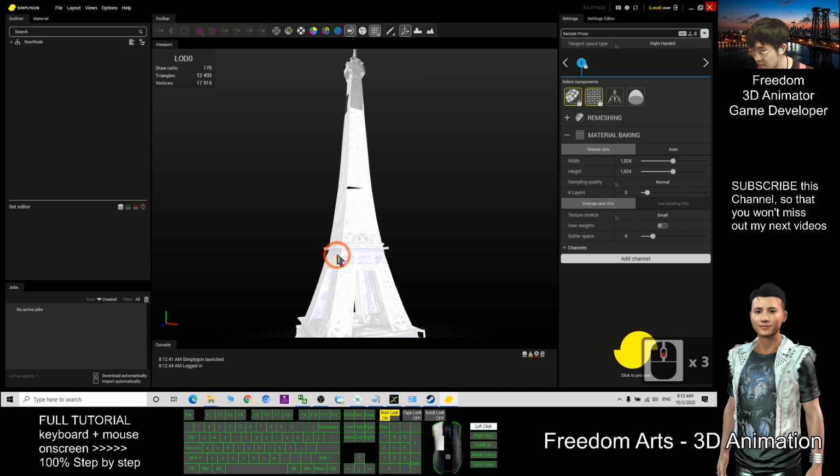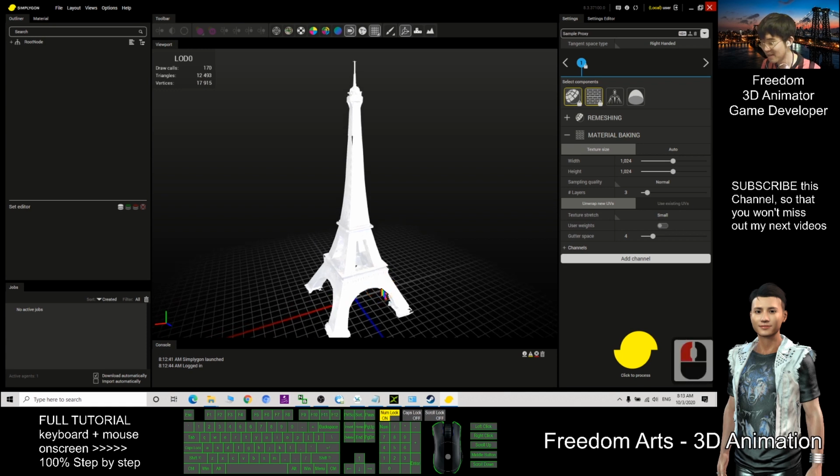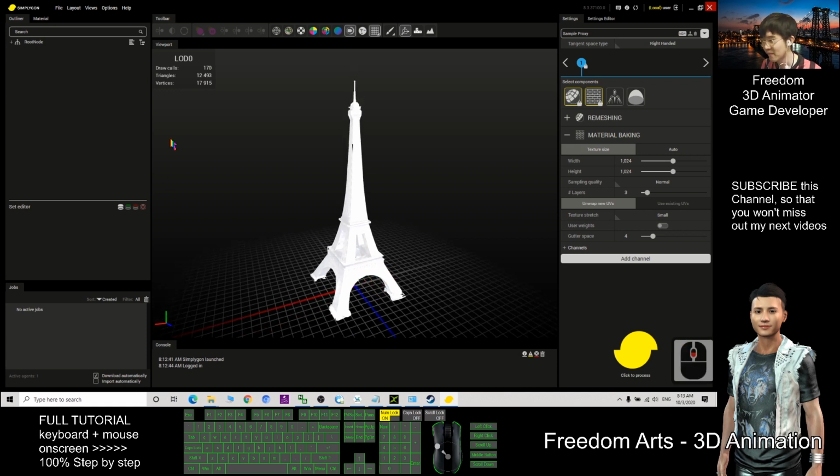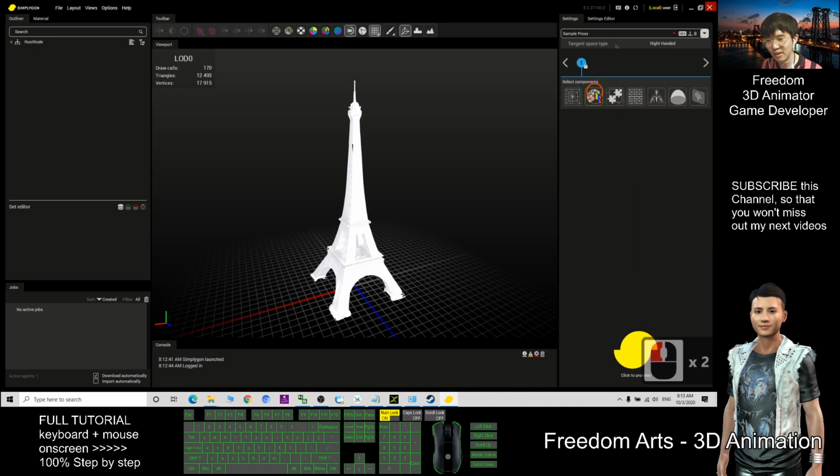After that, you can see the triangles. The number of triangles, the number of faces, is very high, 12,000. It is too high. We want to minimize it to 5,000. Once you have dragged it in, go to the settings editor. Click all the locks to make sure you unlock all of these. Then back to the settings. Then click deselect everything to make sure you clear everything here.